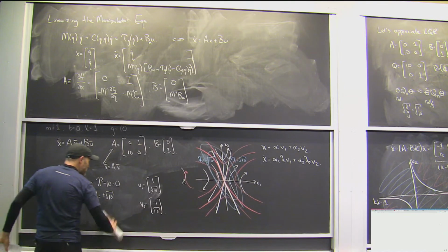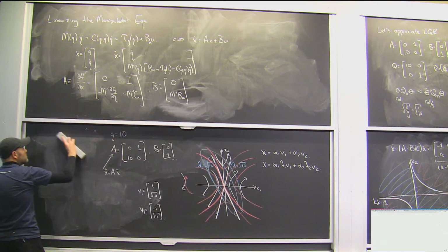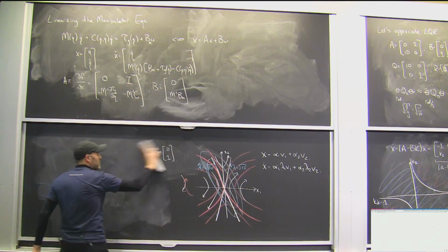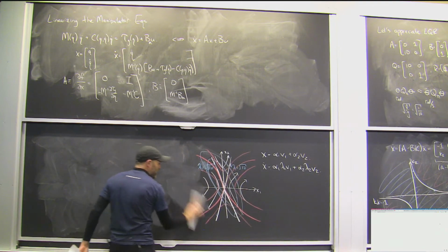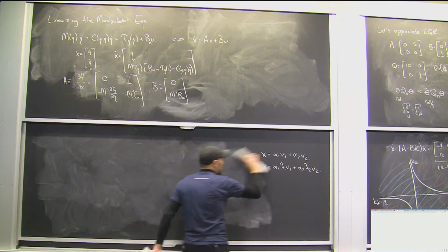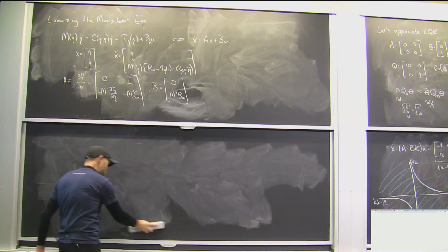And when we get a linearization, so we can get x dot equals Ax plus Bu of the Cartpole or the Acrobot around the top, the next question is, is LQR going to work? You asked a good question last time about controllability.